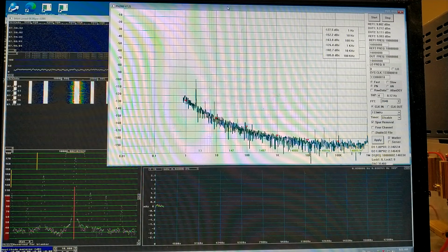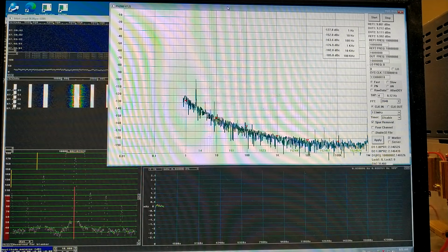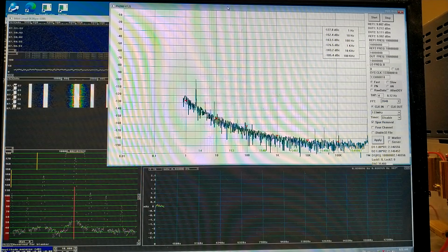I will stop here. The important lesson learned this time is that turbulent air circulation is a problem when building oscillators in big boxes like I have been doing in recent time. Probably the high noise at 0.1 hertz offset in my channel 2 reference oscillator is caused by that problem. So I will try to make my channel 2 oscillator better before continuing investigations on this one.